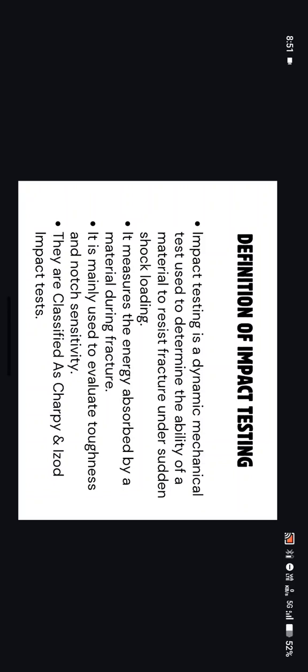What is impact testing? Impact testing is a dynamic mechanical test used to determine the ability of a material to resist fracture under sudden shock loading. Unlike tensile or compression tests, which apply load slowly, the impact test applies load very rapidly. It mainly measures the impact strength or toughness, the amount of energy absorbed by the material before fracture under high strain rate loading. It measures the energy absorbed by a material during fracture.